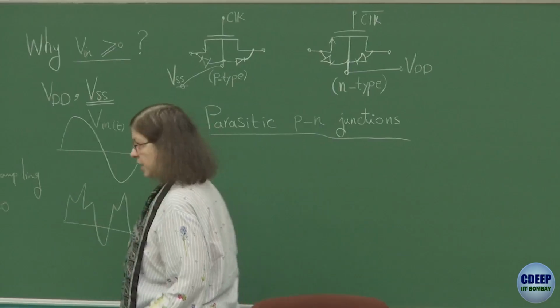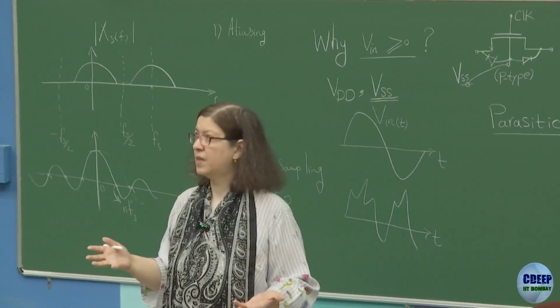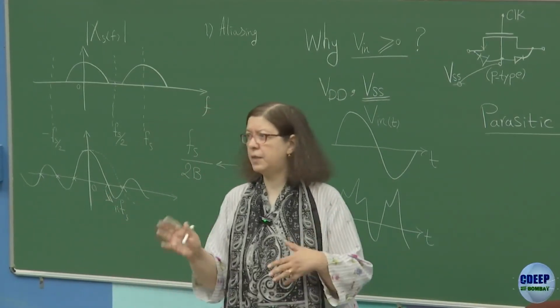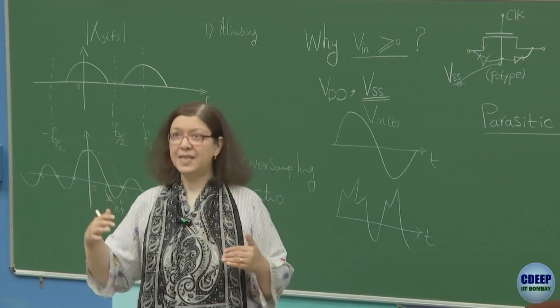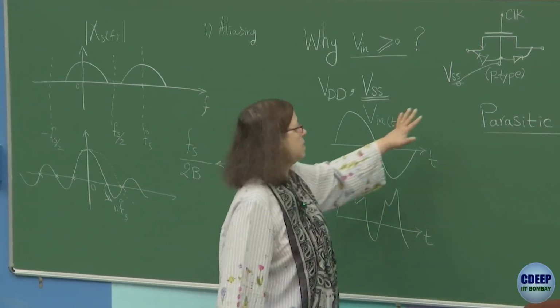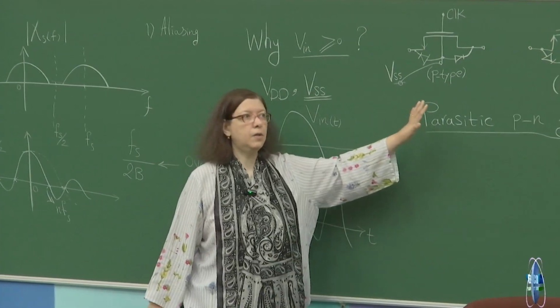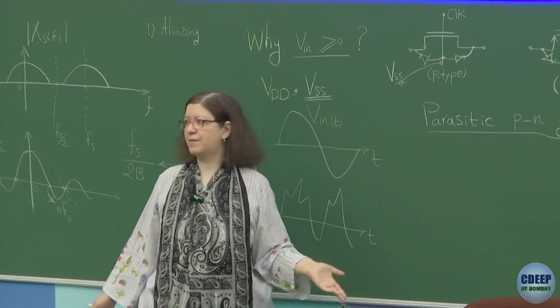Now, if all your signals are between VSS and VDD, which is practical, again, in special cases we design even for signals which may go beyond their supply rails, then these diodes are 100% guaranteed to go in the reverse bias region. Worst case, they will be in zero bias.